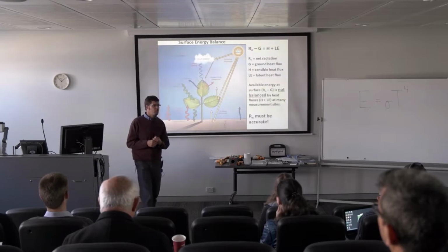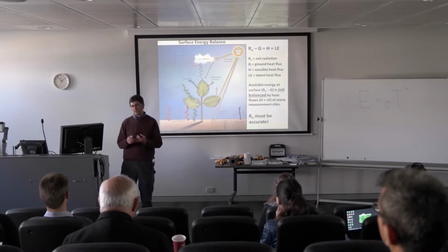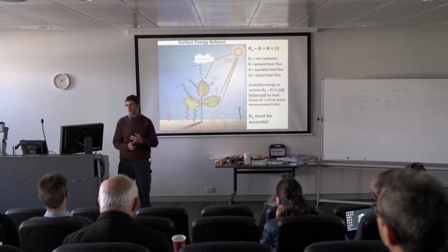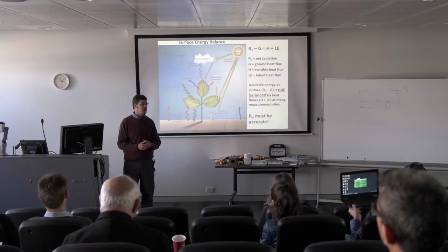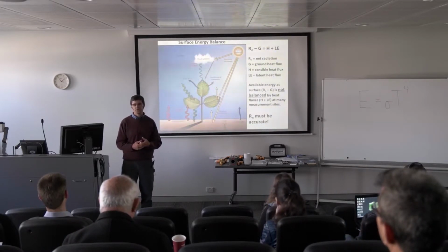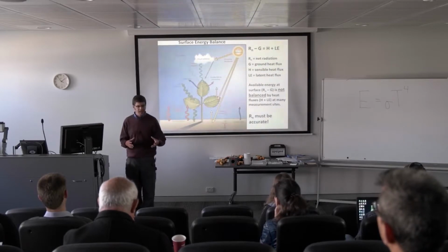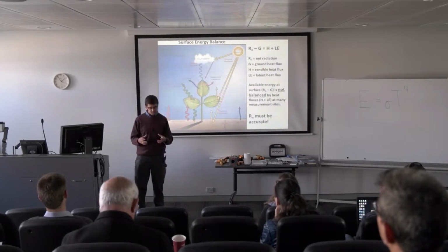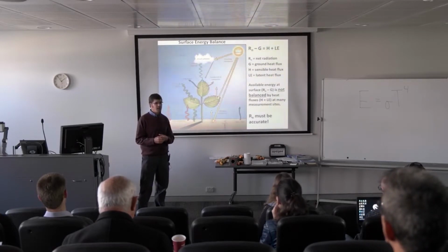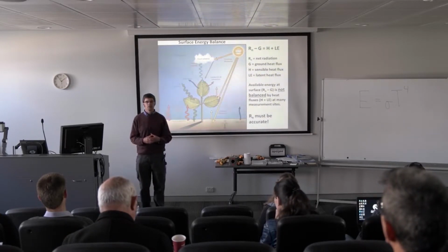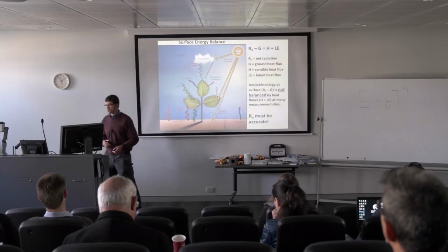When we were talking about photosynthetic radiation earlier, weather stations typically don't have PAR sensors on them to measure the photosynthetically active radiation, and they often don't have a net radiometer on there to measure net radiation. And so you can model net radiation from incoming shortwave radiation, and I'll talk about that in addition to measurements of net radiation with net radiometers.